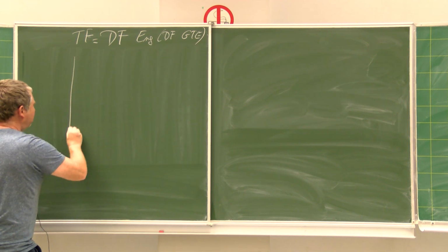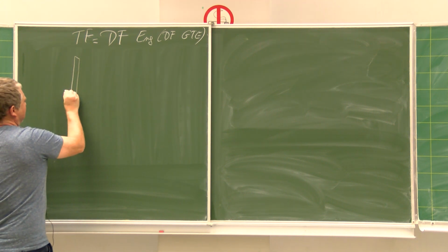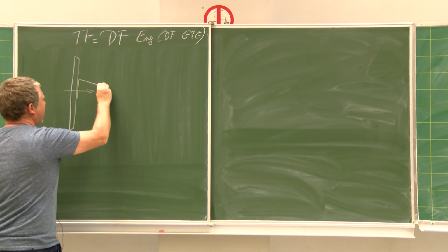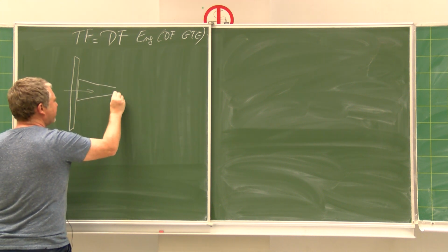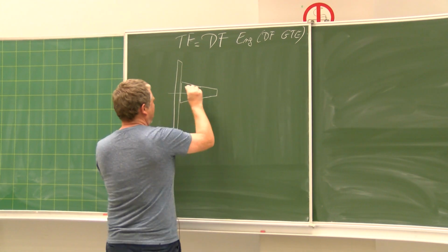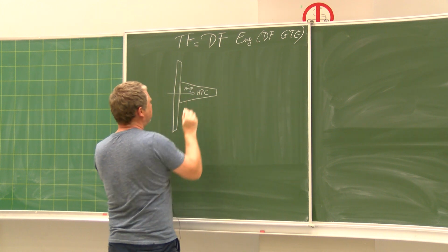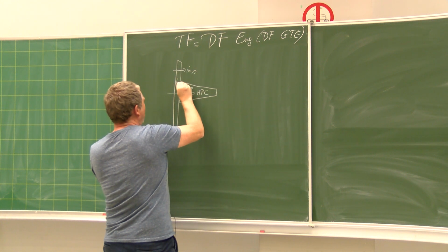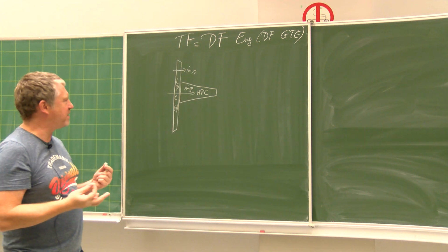The primary flow, which is the central part, will be moving inside the core, as we have called that, of the engine, and we have said that we need to have a very high global pressure ratio. This is the high pressure compressor, where you have the m dot p, and this is the m dot secondary with the low pressure compressor that we have also called a fan, because there is only one stage.